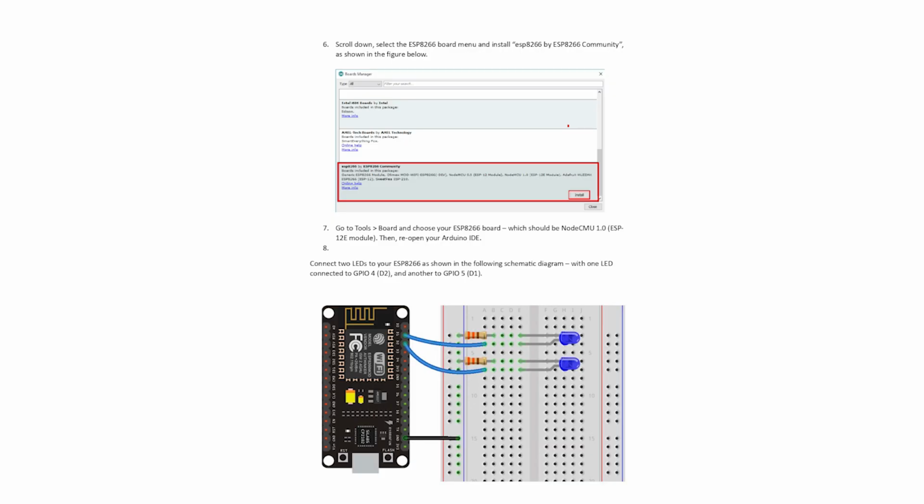So, create this circuit and you will find that this board is a bit too wide. So, what is the trick? This board is so wide that it will actually occupy all of the pins. So, there is a little trick: you just need to place it such that the pins on the left hand side are hanging out and the pins on the right hand side are inserted into the board. Everyone follows?